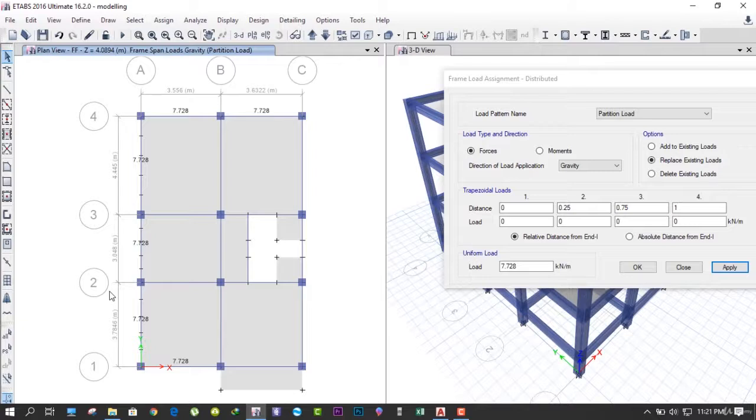So what else you can do is that you can just apply loads on the ground floor and copy those beams to the first and the second floor. Okay, so you have to make sure that all the beams are similar on the upper floors. Okay, the wall over here on the architectural drawing, you can see that is not on the beam, so it is a bit offset with this beam, so we'll apply that load on this slab.